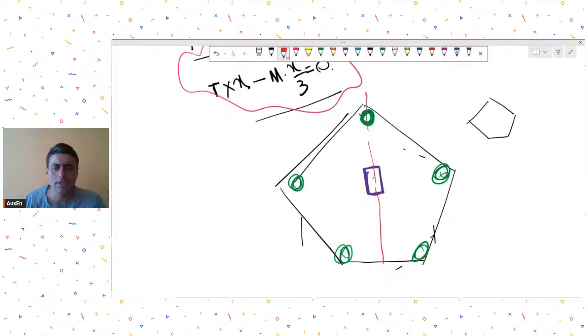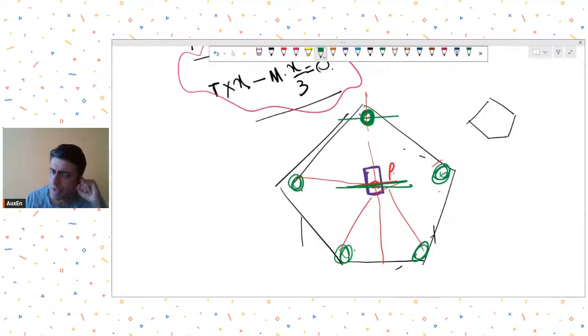Now in such a case, again, if you have maintained it at the centroid, first of all you need to find out the centroid distance, and then whatever is the column axial load, that will be equally divided to all these piles. And then for taking moments, you could take moments about one of the piles and then make that moment equation, and then solve for it. So let's say for example, here now I'm not sure where the centroid position will be for a pentagon. I will also need to check the geometry. But let's say these two piles were having some compression.